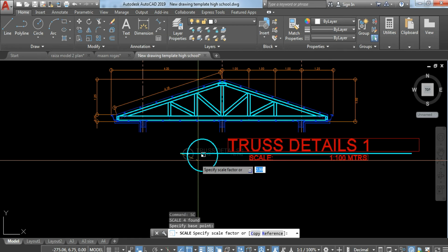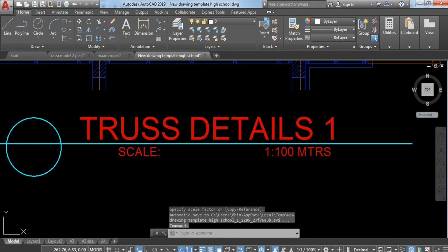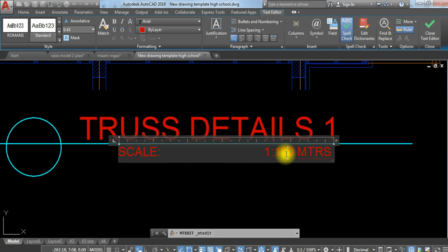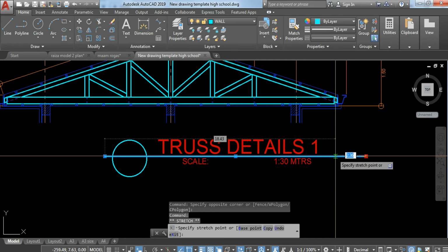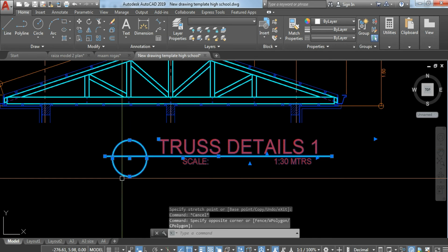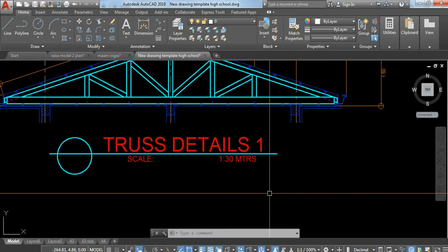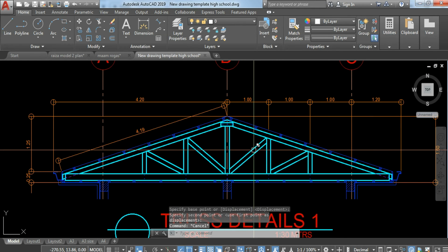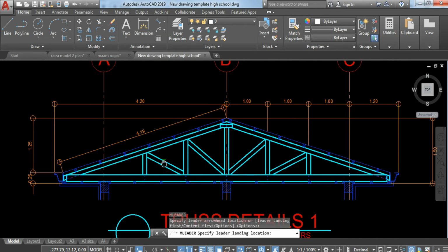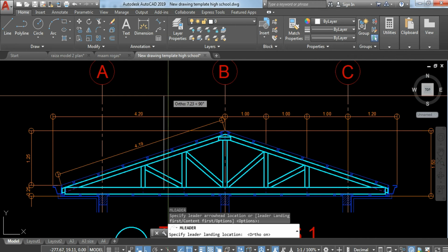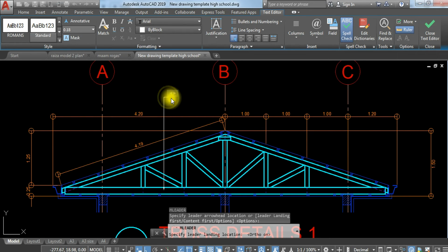Okay? Okay, so if you want to scale this one, then I'm going to change this one because this is already on 1:30. So move. I'm going to adjust this one here. Move the drawing here. And then all you have to do is simply place your details. So MLD, let's try to check if the MLD is really right here. F8. To see if the size of the text is okay. I could also adjust right away our text into 0.25.